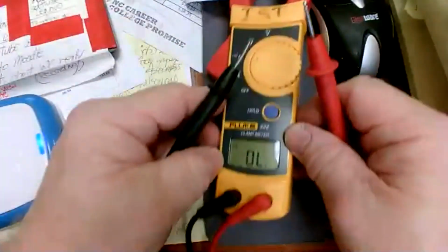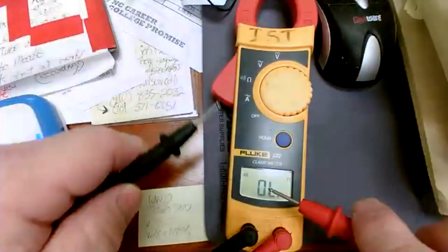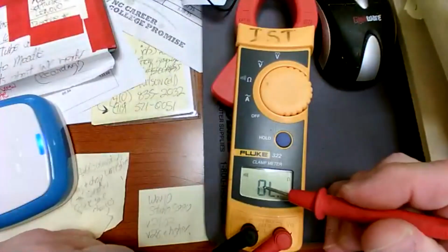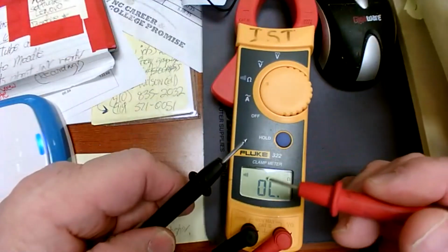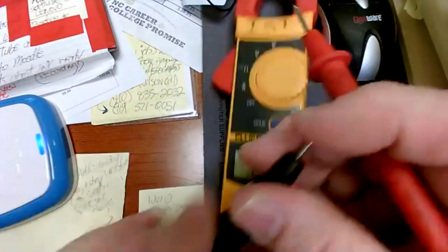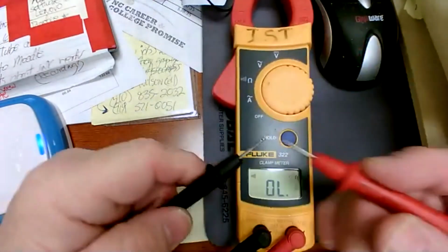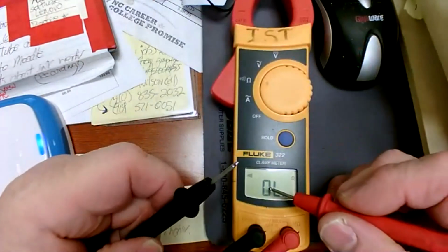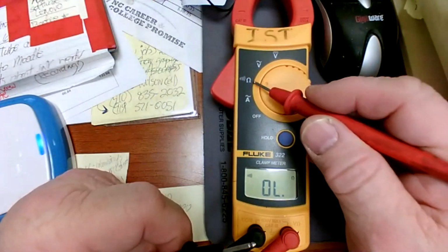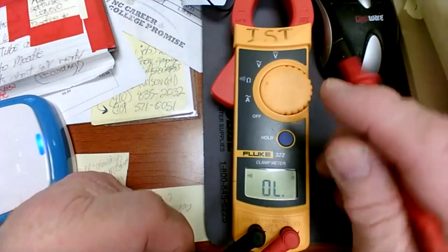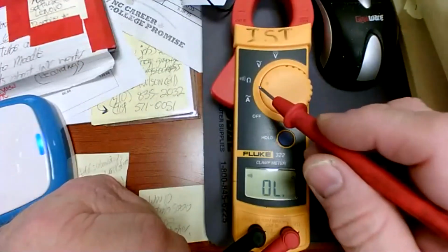So right now, the ohm meter is telling us, it says OL. OL means over limit, and with the leads apart, it can't calculate the resistance because it doesn't have anything to even calculate with right now. There's no circuit. I don't have it touching anything. So I have an open circuit. It's going to read over limit. The limit would be whatever the maximum resistance of that range is. And it doesn't tell me on here what the maximum of the range is. I have to get the little handbook out for it to know.